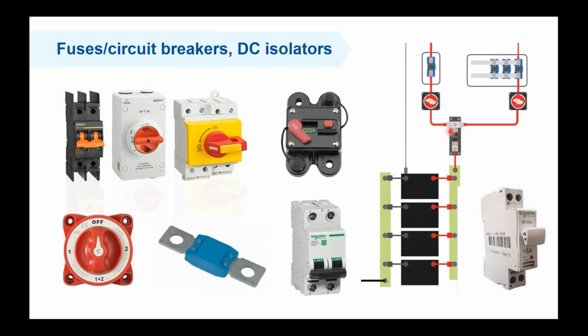Once the fuse has blown, no more current will flow into the circuit, so this is a sort of open circuit, and this really protects. So a general rule here is to share: fuses not only protect the devices and the batteries, but they also protect the wires first.